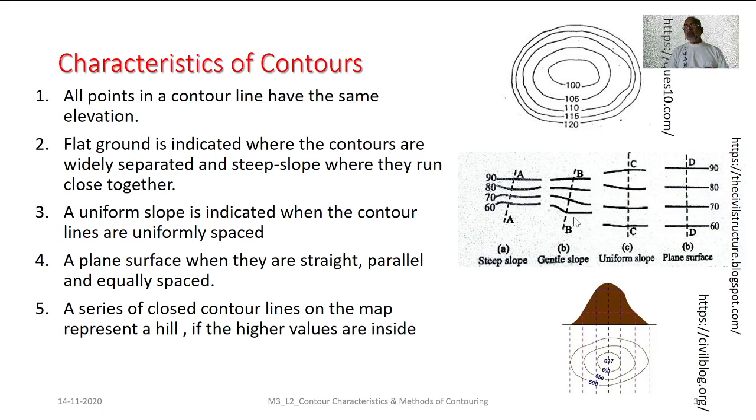As they come closer, they will be presenting some gentle slope. Whereas when the contours are placed very close to each other, they will be representing some broken ground, and the ground under consideration would be of steep slope nature.